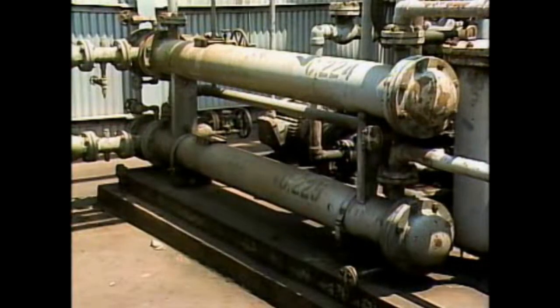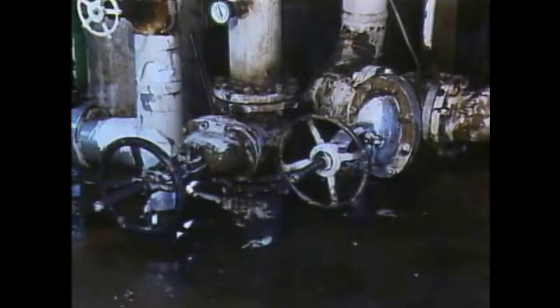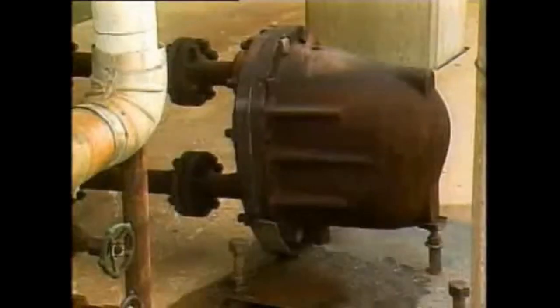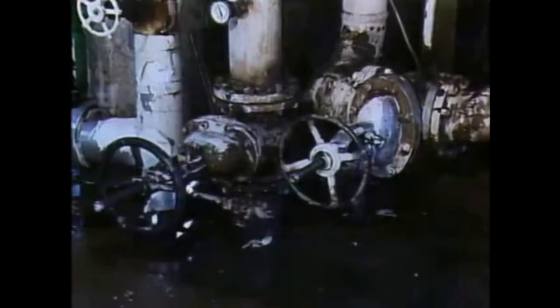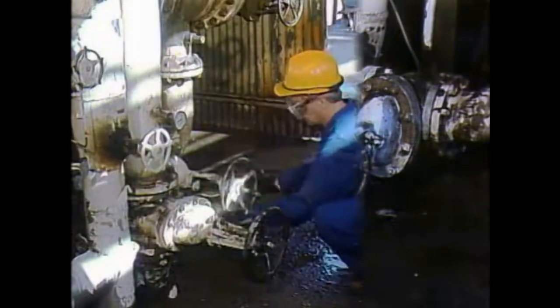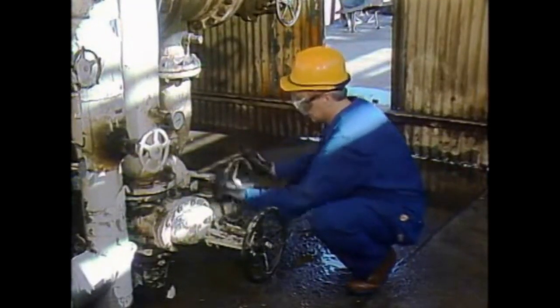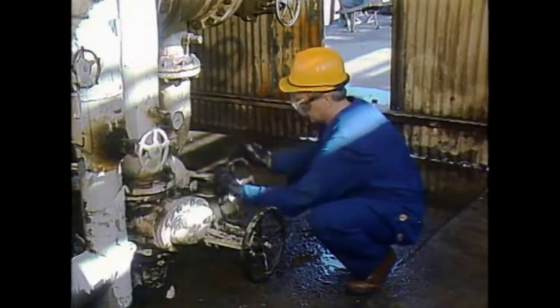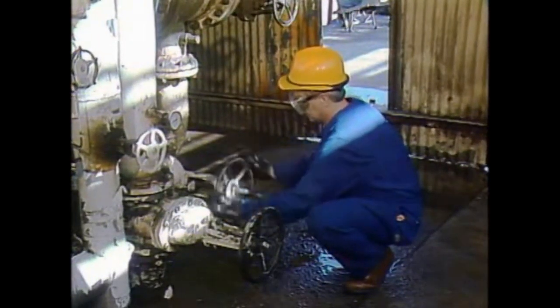In order to get fluids into and out of a heat exchanger and make sure that heat transfer occurs efficiently, some auxiliary components are needed. These auxiliary components include valves, instruments, and steam traps. There may be many different valves used with a heat exchanger. For example, isolation valves may be located on a heat exchanger's inlet and outlet. They're open to place the unit in operation and closed to isolate the unit when it's taken out of service.